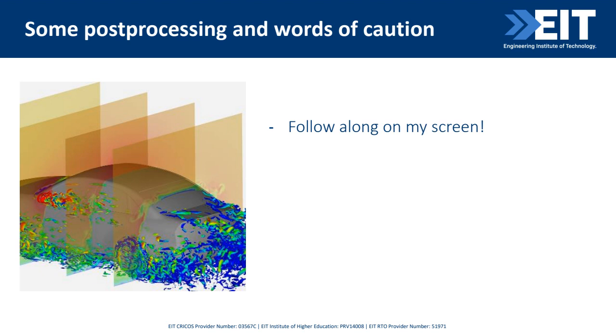So a word of caution: just because it looks pretty, it's a colorful diagram, does not mean it's true. Taking the dam break case, for example, you should go over mesh independence, and you should validate your case against either experimental values or analytical values. That is something I can't stress enough, because unfortunately, CFD also stands for colorful diagrams, and that could be all it means.